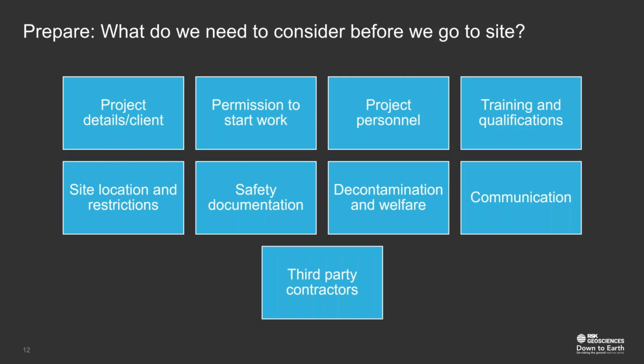Are there any site locations and restrictions? So where is the site? Do you need to consider booking hotels? Can you access all the places? Is there any soft ground? All things we mentioned earlier that you can get from your site walkover. If you have got a site engineer and you've identified them before that walkover, it can be really helpful to take them with you so at least they can have a look at the site before they go.